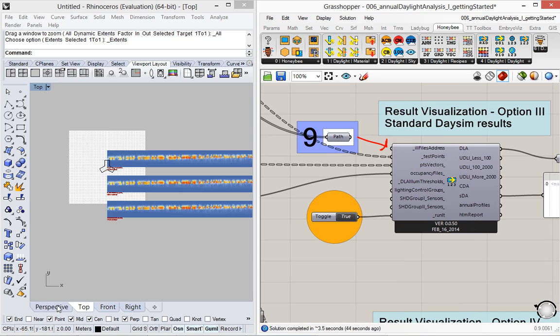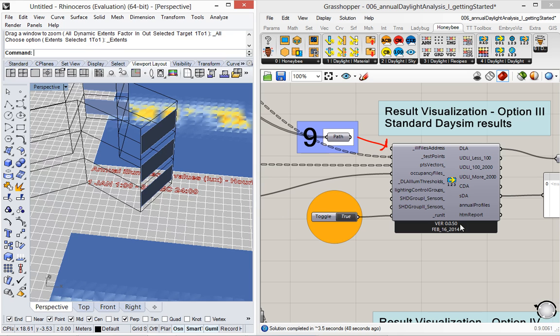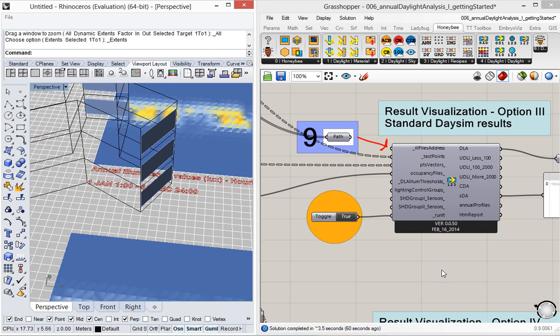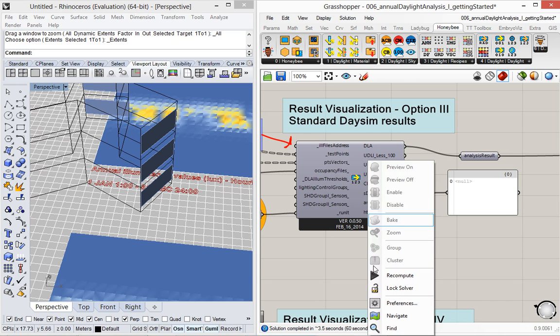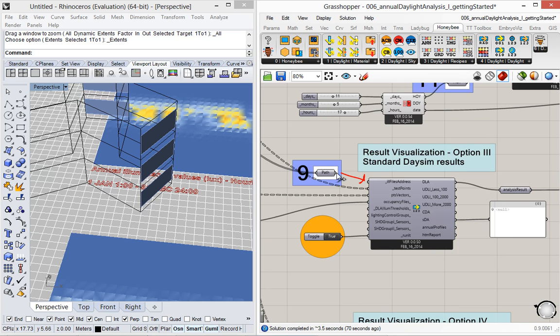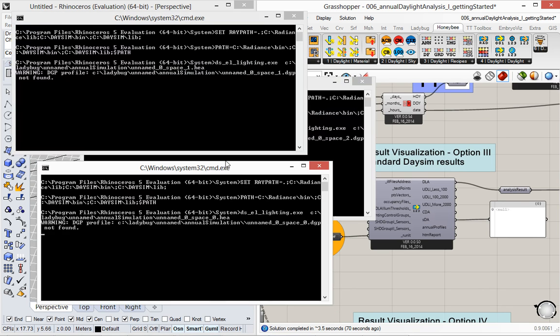So if you're running something like this and you want to get the profiles, like the lighting profiles and all the calculations, you really have to run it three times. But I tried to use the data management in Grasshopper, and every single branch is basically a different space, so I just recreate the heading files, all the stuff. As you see, you just pass it once and it gives you the result for three different spaces. You can't see it because I disconnected that, but that's why you get three different batch files.